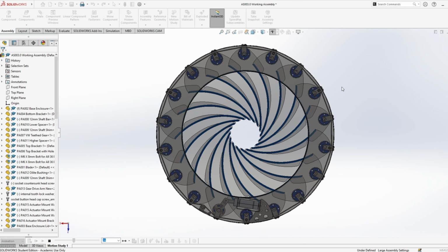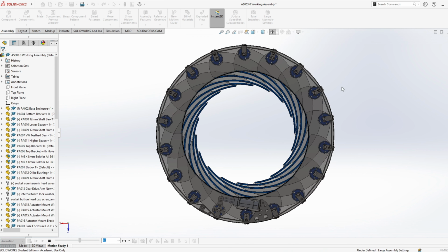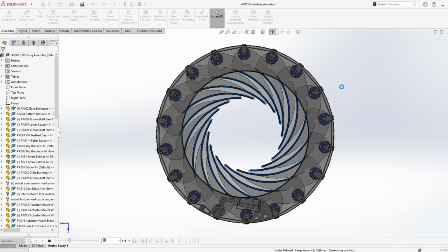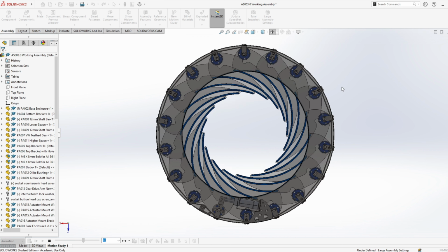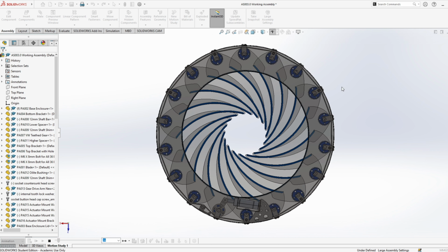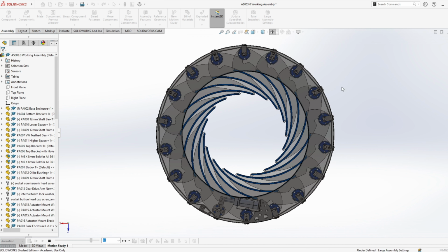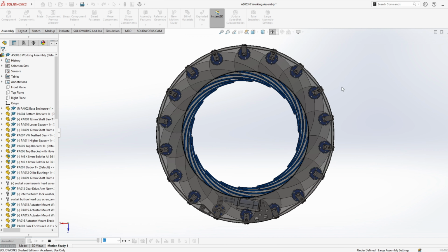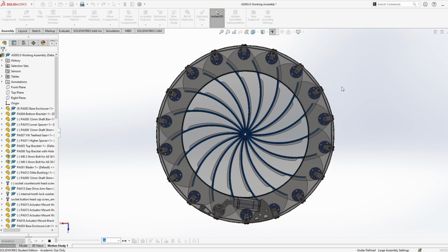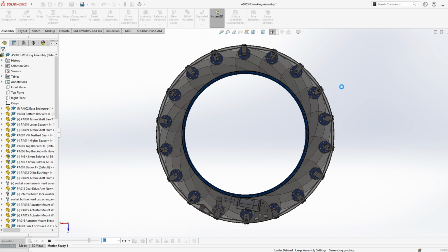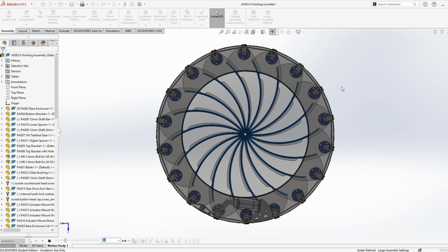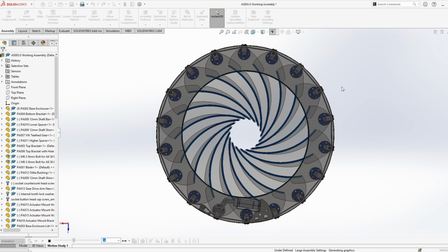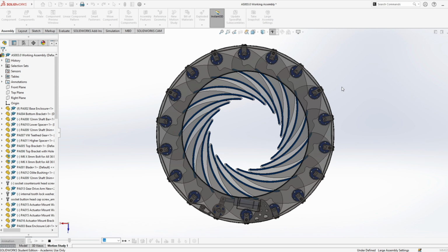So if you imagine this base enclosure being manufactured from a weaker material and not the 2mm stainless steel which I have selected, there's a chance it could distort or even buckle or crumble from the stresses, strains and forces exerted on it by this drive belt. For example, if the enclosure was manufactured out of 0.9 or even 1.5mm stainless, it's very likely that this design will not handle the alternate forces within the drive system or the high tension that's required on the large belt to keep the system in sync.